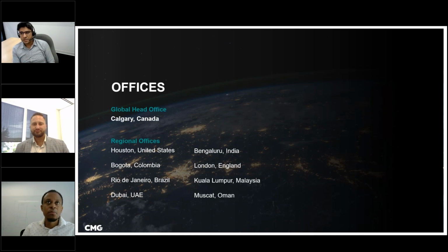On top of this, a recent addition that we had at CMG is called grid independent wells. Traditionally the wells are defined using the IJK addresses, but a very interesting tool that we have added recently is grid independent wells. Let's say you have a deviated well and you want to know the best direction of the well. That would be hard to define using IJK values and then define which grid blocks in the reservoir are perforated.